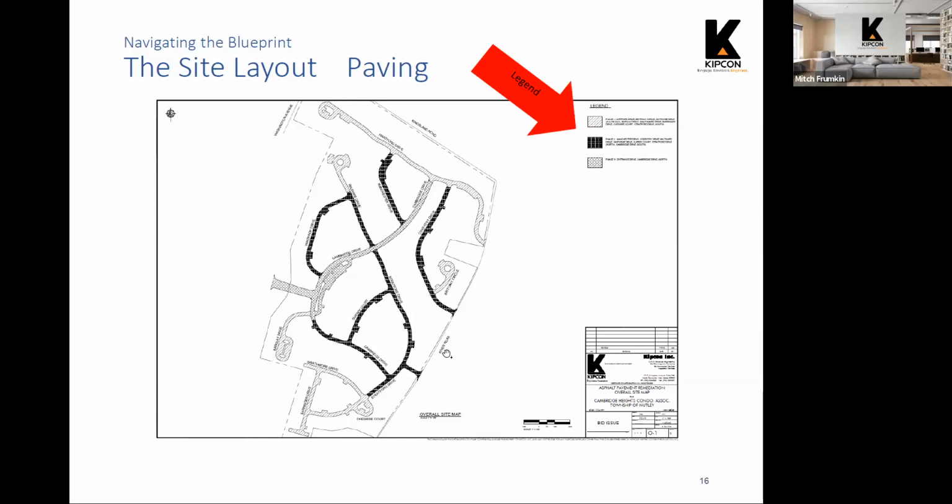And you'll notice there's a couple of things. There's a north arrow that shows which direction obviously is north. And there is also a graphical scale. So drawings are obviously much smaller representations of what's in the field, and on civil plans or site work plans, they'll give a scale in 1 inch equals so many feet, and depending upon the size of the site or what the area of earth that you're trying to represent, those scales can be 1 inch equals 10 feet, 50 feet, 100 feet, 200 feet. So those are the scales for site work.